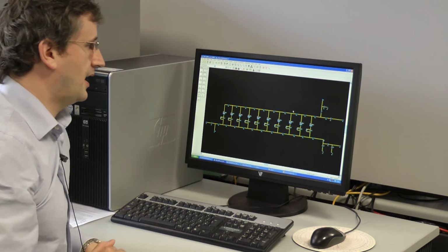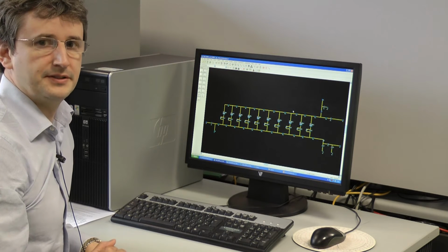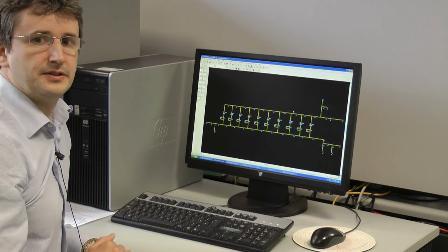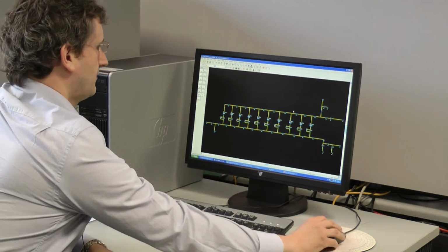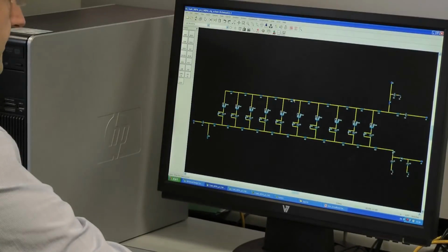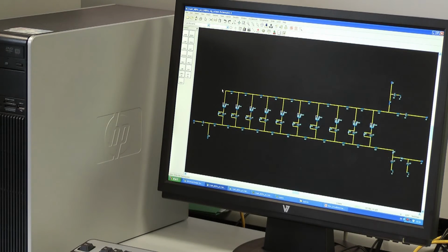We have tapered the drain line characteristic impedance so that they do see close to this optimum impedance for power. This is the drain line here. Notice that the drain line termination resistor is not required in our design.